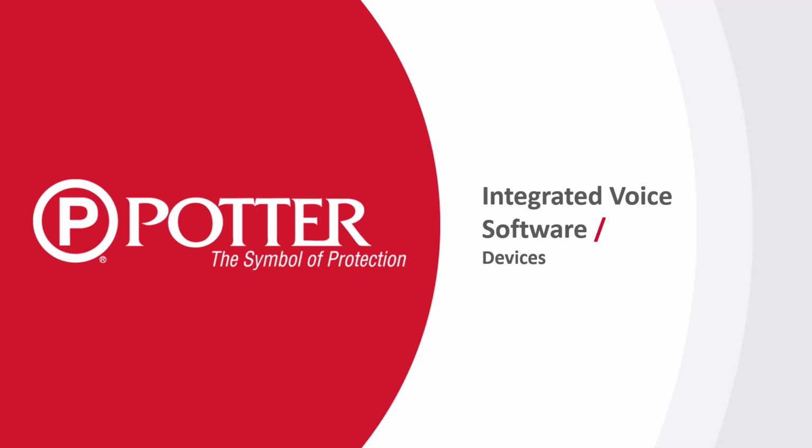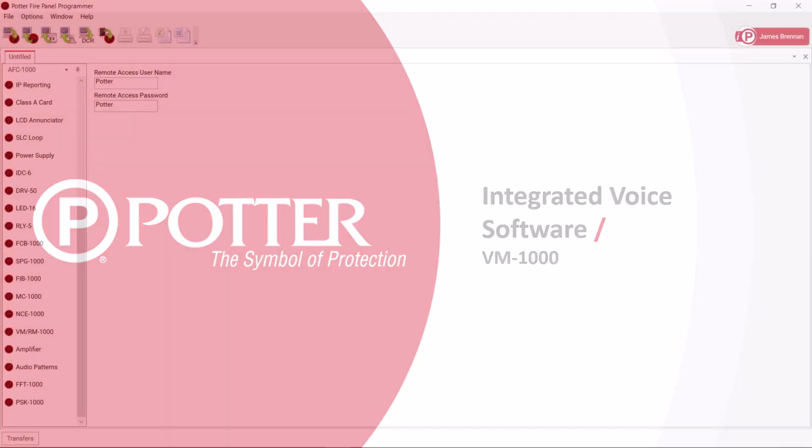This video covers adding integrated voice devices in the PotterFire panel configuration software and their associated settings. This section explains the VM1000 module, outlining its role in the voice evacuation system, configuration settings, priority control features, and how to add modules like SB24s, along with detailed options for adjusting microphone and auxiliary input settings, are also discussed.